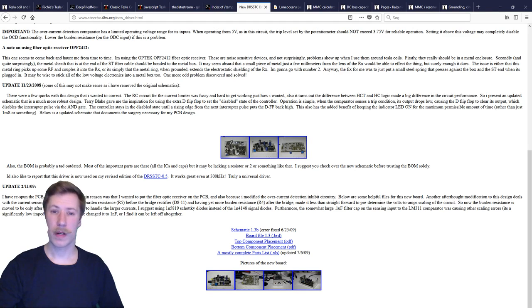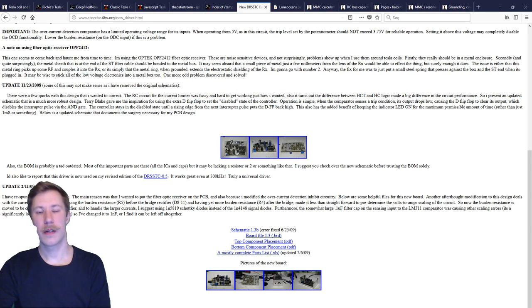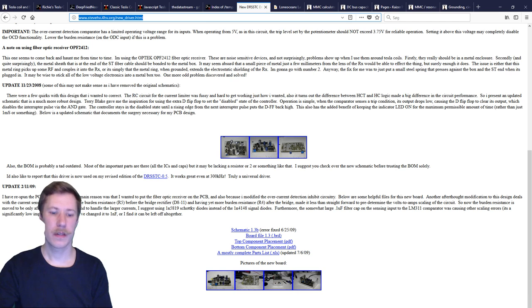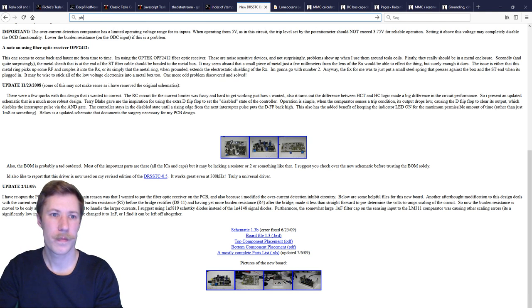And I would recommend using this for anything when you're not talking IGBT bricks. As long as we are talking small, fast IGBTs, there's really not that huge need for phase lead. But if you are using large IGBT bricks, there's of course use for phase lead, as this will lessen your switching losses.